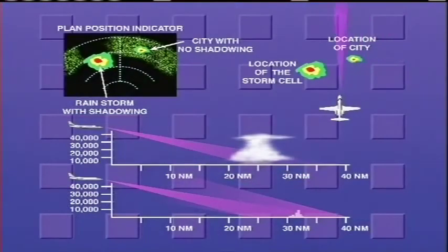When attempting to map sea returns, be aware that calm water provides a very low radar reflection. It acts like a mirror and reflects the pulses forward and away from the receiver. The same is true when viewing the sea from a direction parallel to the waves. A much stronger reflection can be observed when viewing the sea in the up and down wind directions, the upwind being the strongest.